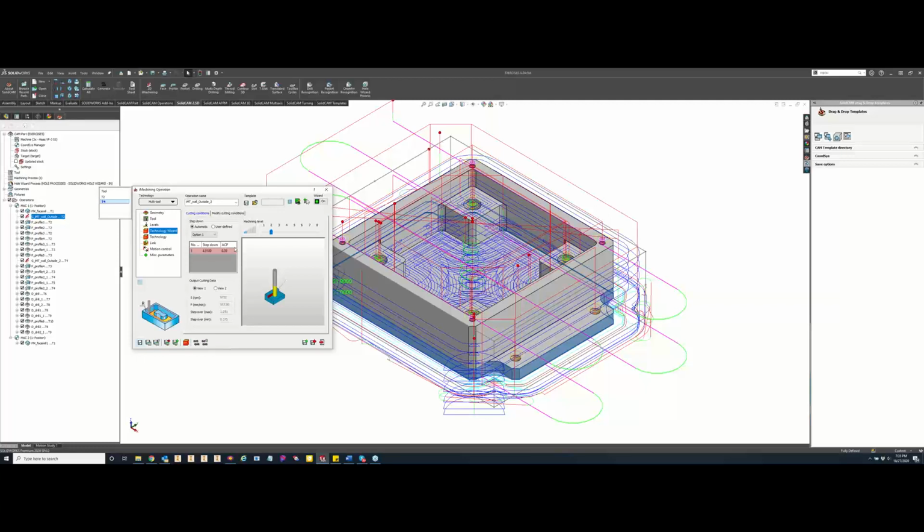Now, we've been talking the last couple of weeks about feature recognition, chamfer recognition, pocket recognition, iMachining with all the recognition. One thing that will definitely help you out is, let's say I make a change to something up here, then you'll notice that some of my operations down here get out of sync, and they put a little star there. So instead of hitting your save and calculate button, move over one and do save and calculate with related. What it will do is automatically calculate the ones that get out of sync as well.